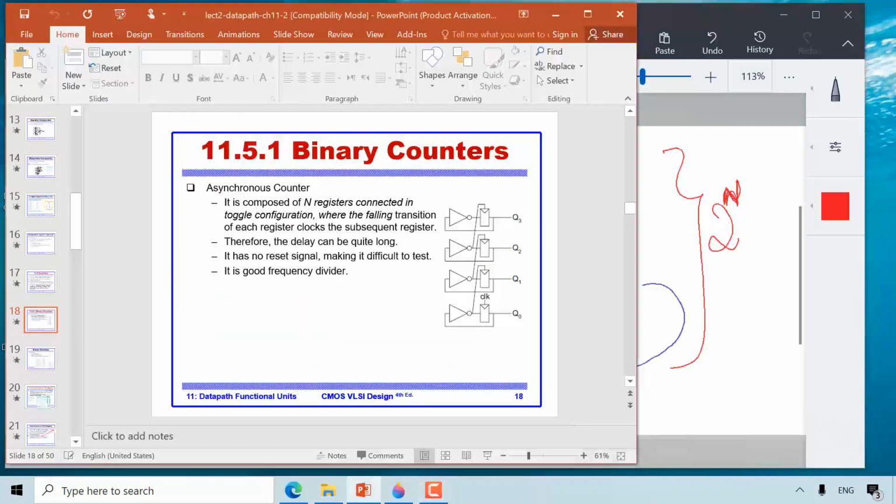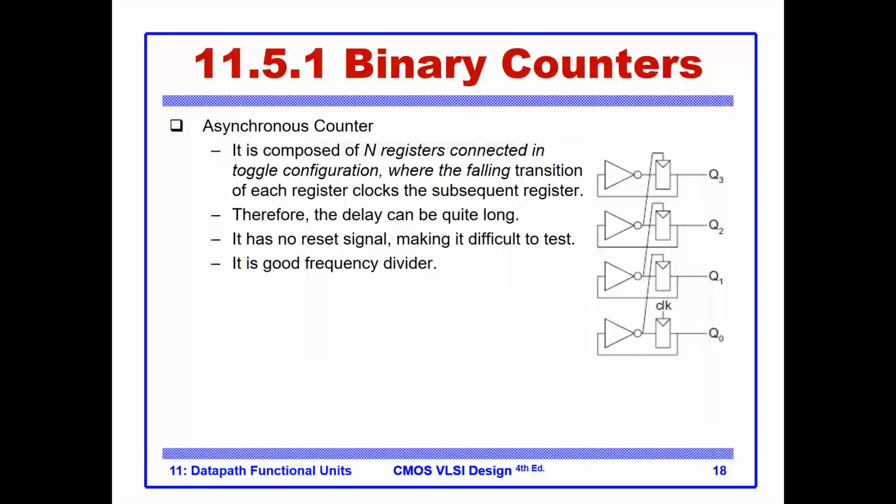Okay, so that is about the asynchronous counter, which we basically call a clock divider, and it produces different clock frequencies. In digital systems, it is quite often that we need to design the system with separate clock frequencies. Okay, so this is one circuit that does that.